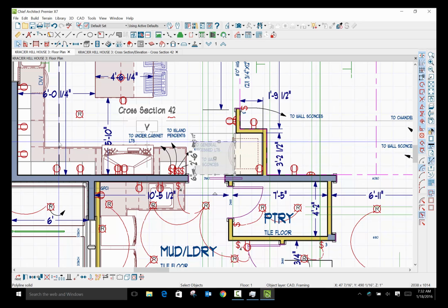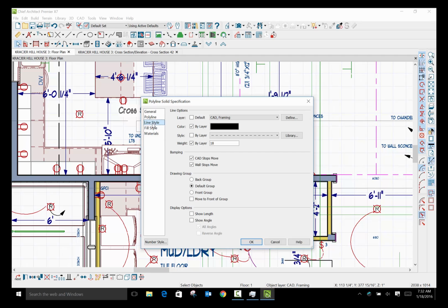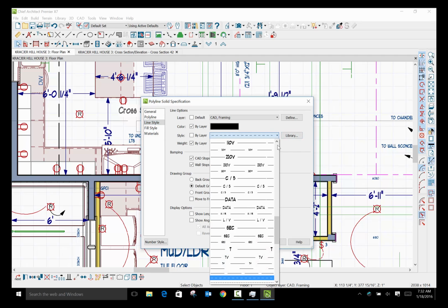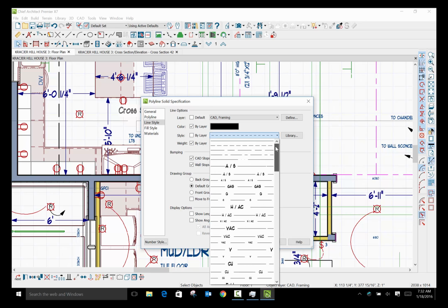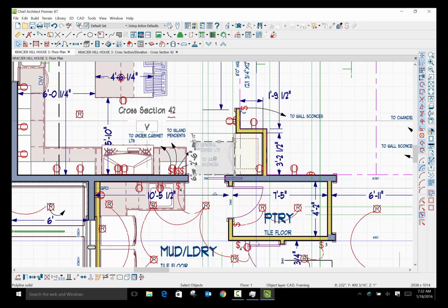This is using these big fat lines. Maybe we should just use the big fat lines line style, which is more like the default. I think it's that. Yeah, and it's got a line weight of about 40 actually. 35, 40. Let's go 35. Just about that. And yeah, close enough. All right, there's that guy.